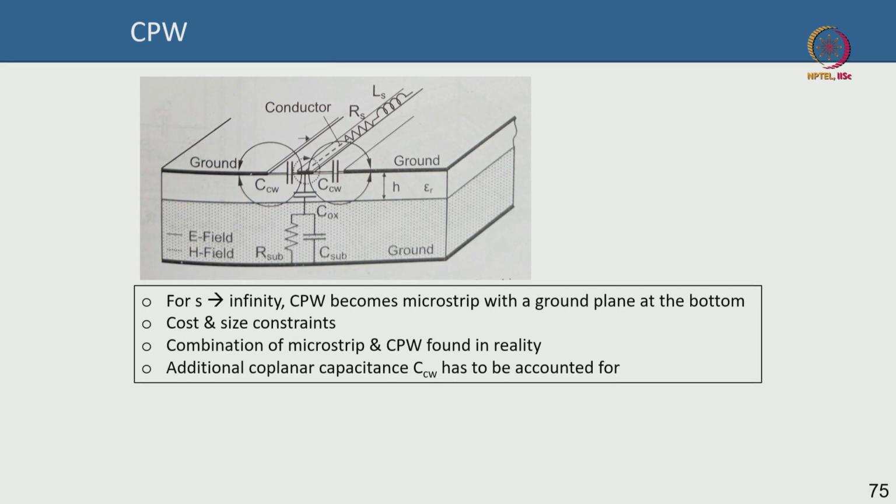Now if I look at a CMOS process and not a compound semiconductor process, then there is an oxide here, SiO2, and then there is this silicon substrate. Although the silicon substrate can be HR, which stands for high resistivity silicon substrate, and by high resistivity you mean around 10,000 ohm centimeter, which is high resistance, technically it is not high resistance for RF. At high frequency RF signals, it actually is very lossy, so that loss in the substrate is much higher than in a semi insulating gallium arsenide or gallium nitride substrate. So silicon CMOS based processes will have a substrate loss, which you model as a parallel combination of the substrate resistance and the substrate capacitance, existing in shunt to each other.